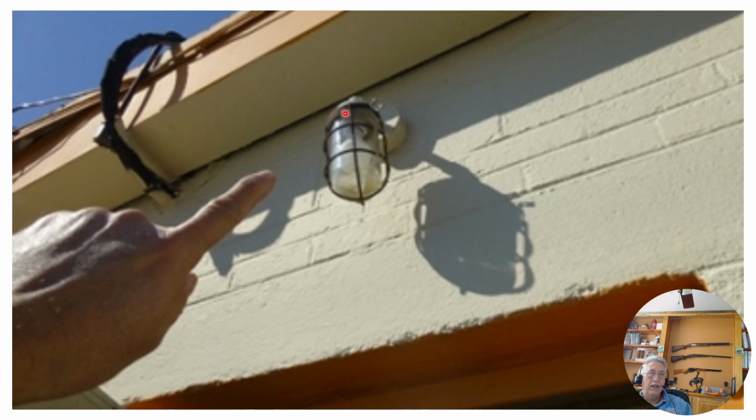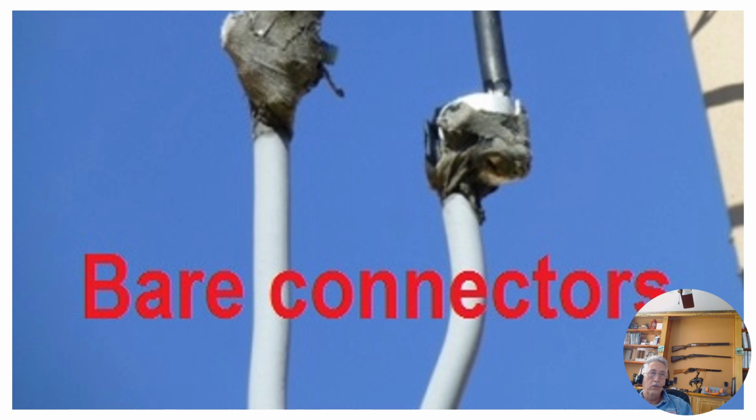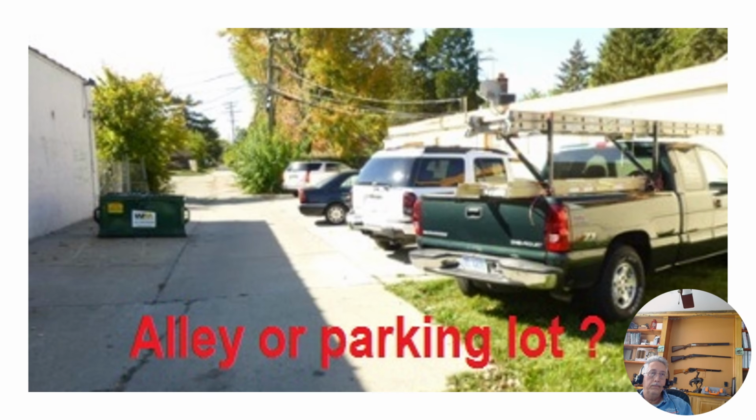It's got a globe over it, and we don't take globes off to test with a hot stick. If I could have gotten my hot stick or voltage detector in there, I would have used that to see if it was hot or not, but it wasn't. And that's the condensing line going up to the air conditioning unit on the roof, I believe. The masthead had some bare connectors on there, so I give it the finger like that to show where the problem is. Then I go in closer for a shot like that to show the customer exactly what's wrong.